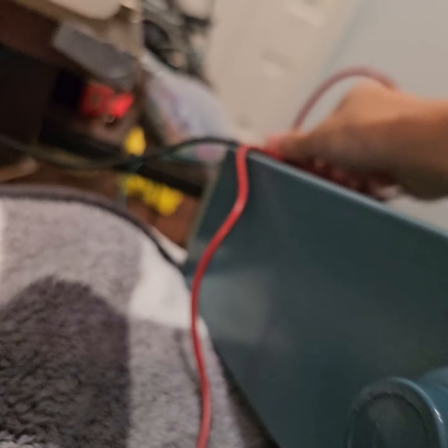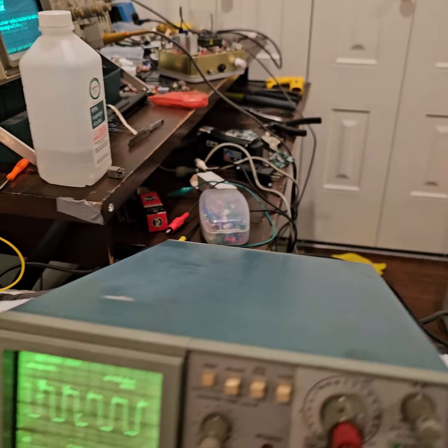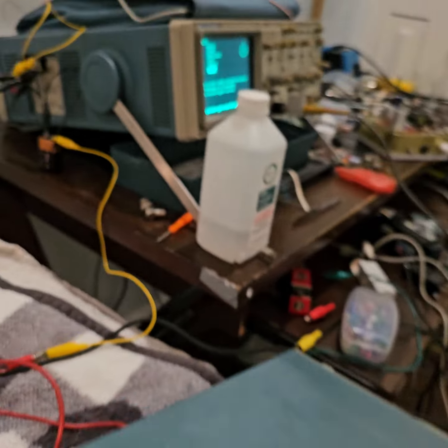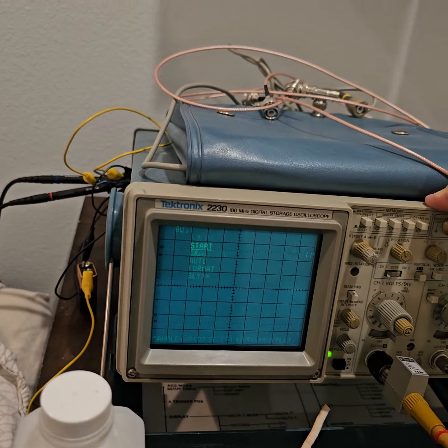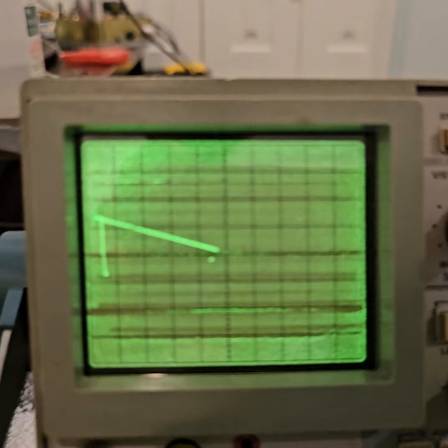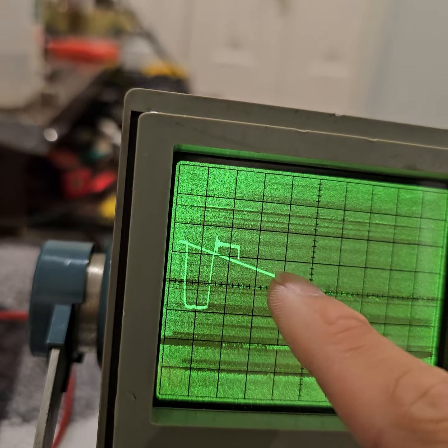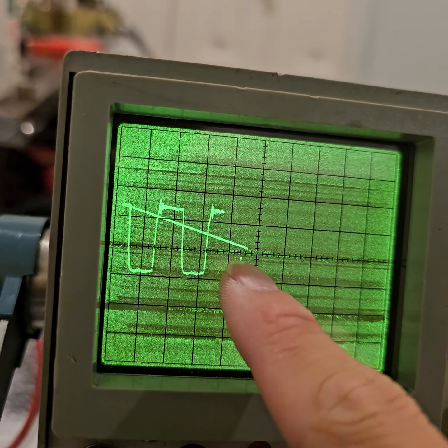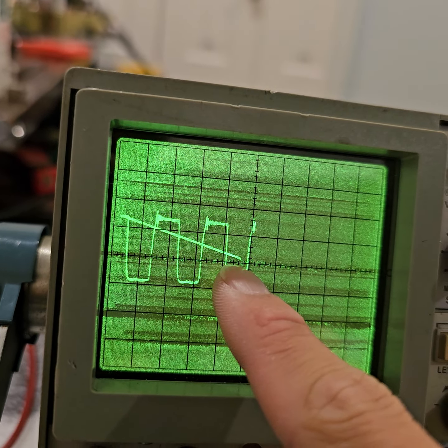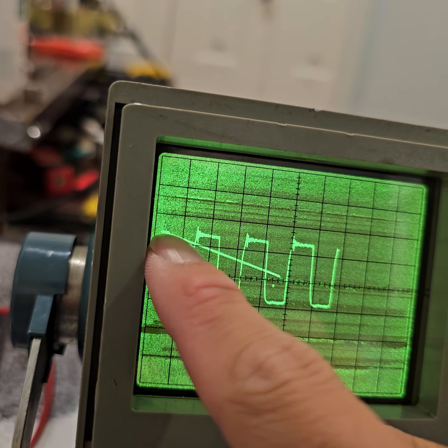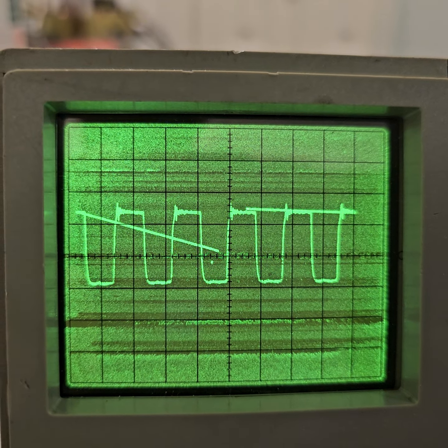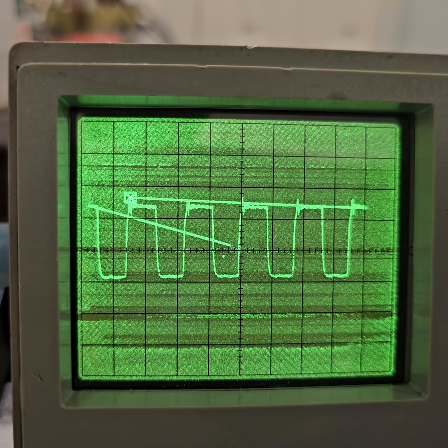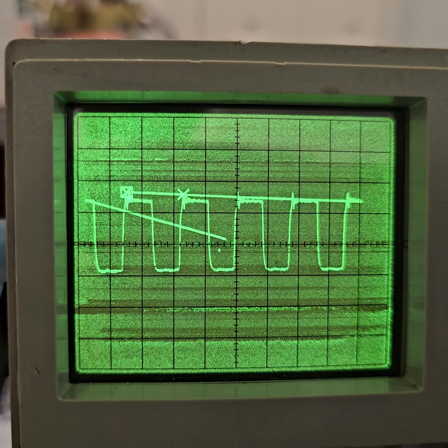Let me show you what happens if we don't have the z-axis. It'll produce okay results, but not the ones that are typically desired. You'll see. Look at this. Already. You see this line? It went from the center position, and then without the beam blinking, it drags along and draws here, and then it starts to draw the waveform. Look at that. It's retracing back to draw the cursors. This is why the z-axis is important.